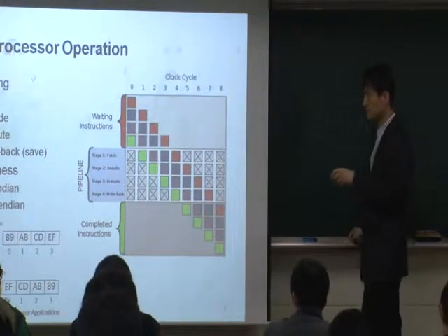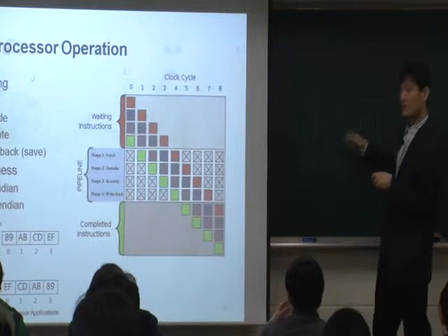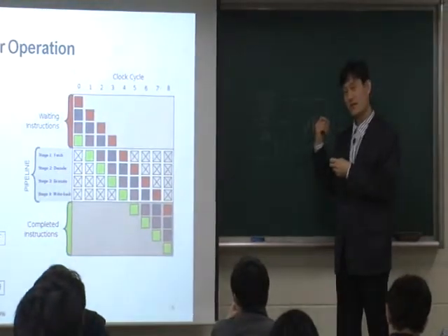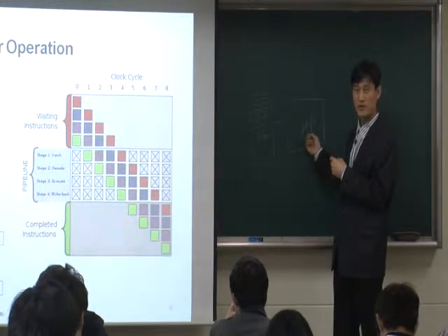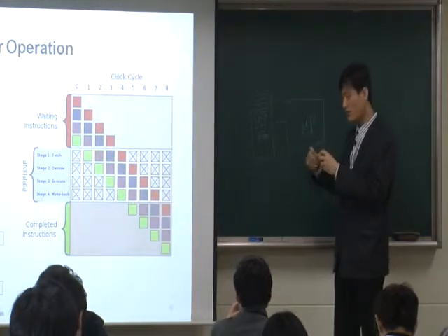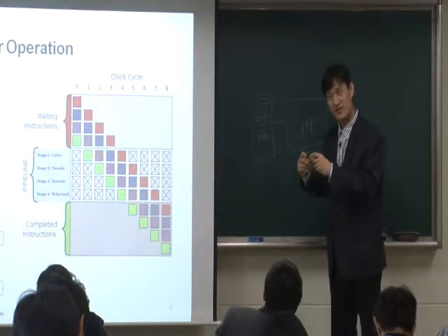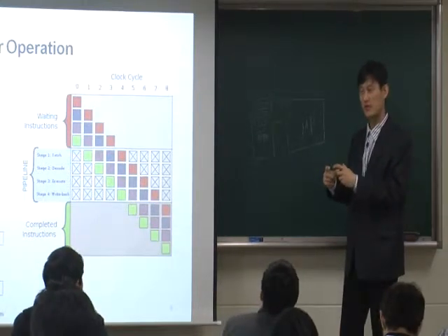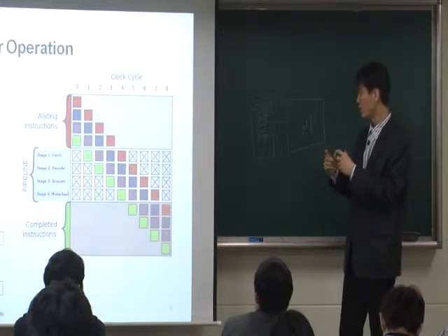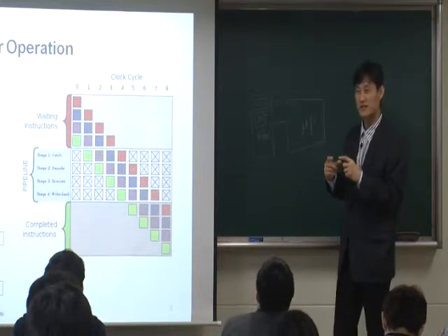That's fetch. Once the microprocessor fetches it, then it should do decode. What is decode? The microprocessor will look at what instruction it is. It may be add, or multiplication, or store, right? It has to know what it is.